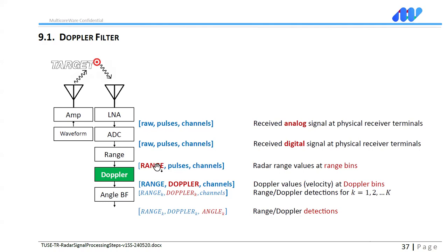Data cube size didn't change, as you can see. It's the same data, but range is being processed. And the step is basically the FFT of the range data. The whole data is the same size. Then you come to Doppler processing. Once you process it, you play with the second dimension. Again, it's the same data. You play with the same data.